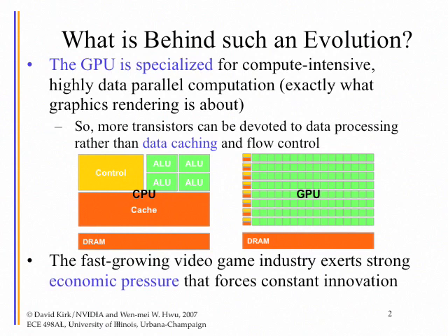So you have a huge number of these execution units, and now you have a little bit of a problem. Because not a whole lot of data is sitting in the on-chip cache, you will have situations where you have to go out to the DRAM to get that data. So right from the beginning, you design for DRAM latency.